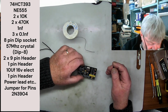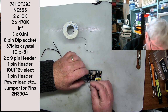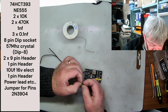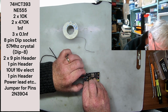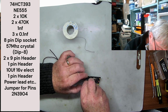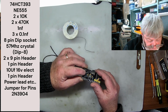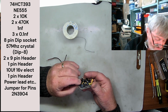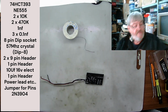Okay, have my 2N3904, and I'll only follow the pattern on the board and put it in that way. Put it the other way around and it's not going to be happy. You just need to splay the pins a little bit for it to pop down the holes, and it'll just pop in. You can push it down as far as you want. You don't need to go too crazy with it. And then I'll just solder that in.